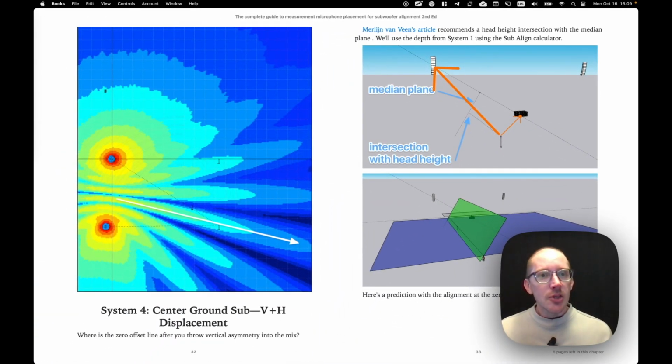You may have already known that, and I thought I knew that, but what I only realized recently is that just by the sheer existence of that point in space in the audience, we don't need to do distance measurements, right? You only need to do a measurement here and put your microphone here if you don't know the pre-alignment delay values.